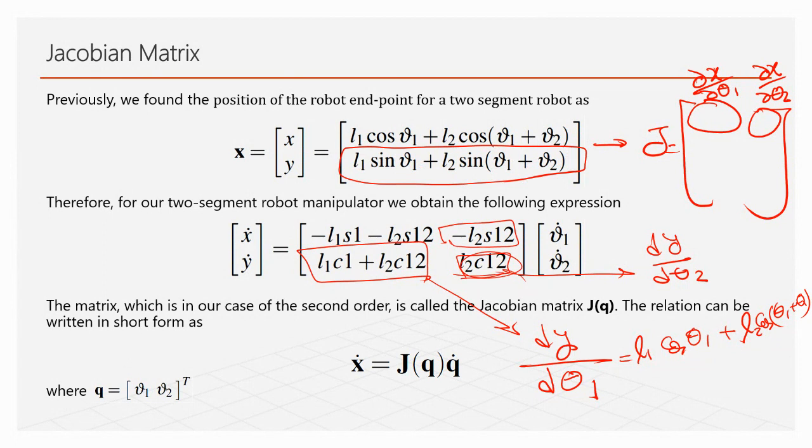So you see there is a mathematical concept beyond the Jacobian matrix. What we introduced as the Jacobian matrix initially was based on our understanding of what happens between the velocity at the endpoint and the rotational speed or velocity of the joints. But it comes from a stronger background when you want to do a multidimensional system analysis. Any questions so far?